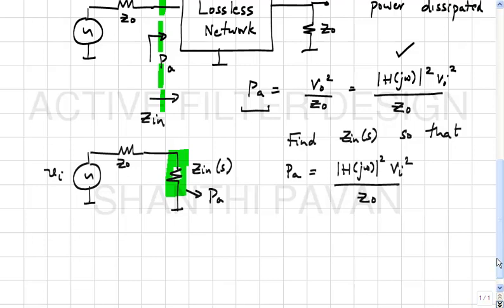Yes? Okay. So the nice thing about this is that you have now reduced the problem of finding a two-port to determining a one port, which is a single impedance. Presumably working with one port is much easier than working with two ports, because in a one port you only have to worry about Z of S, whereas in a two port you have to worry about three parameters. Okay, and what we have done is exploited losslessness of the LC network. Does this make sense so far?